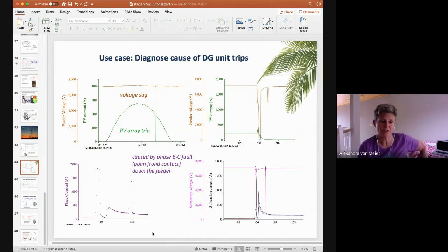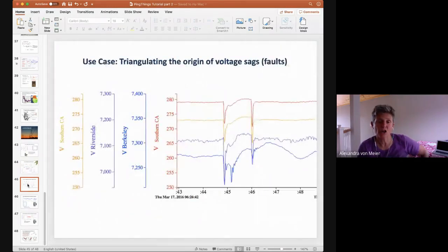And these types of diagnostics are not relying on angle. Those are simply high resolution magnitude measurements. I showed you correlating voltage magnitude measurements on different phases in the Bay Area. This is only a single phase, but showing you the relationship between Northern and Southern California. And the fact that when there is a big fault somewhere that creates a big disturbance, you can see it in different places hundreds of miles away, which is kind of cool.